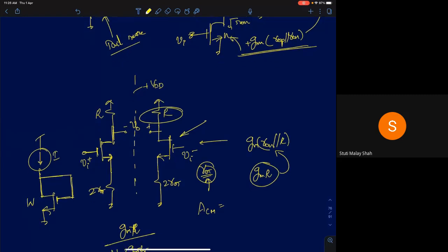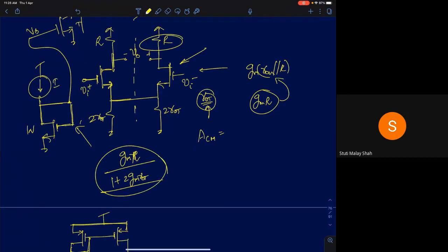One of you is asking, ROT is the output? Yes, exactly. ROT is the output resistance of your tail transistor. So we had this current source, the tail transistor. This is V bias, and V bias is generated using this diode connected device. This transistor's output resistance is ROT, the resistance looking into the drain of this transistor. So we have so far discussed common source amplifier configurations. I've also introduced what happens when in practice you will have a tail current source whose output resistance determines what your common mode gain is.